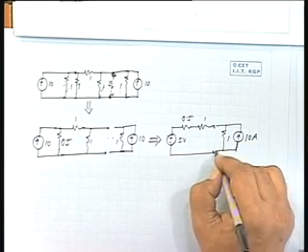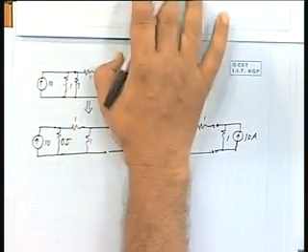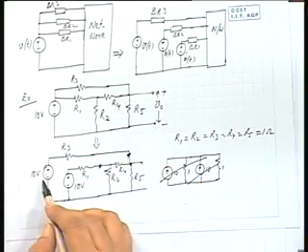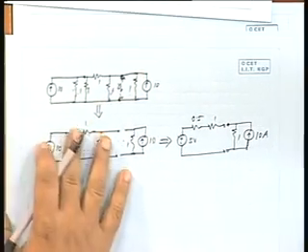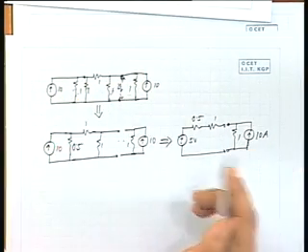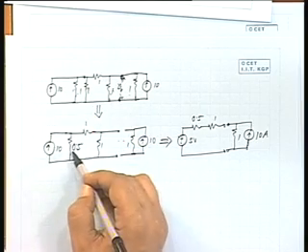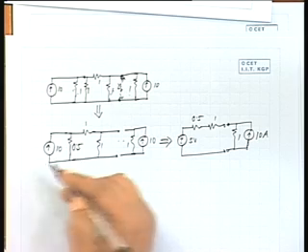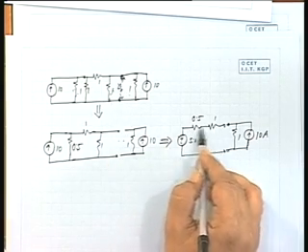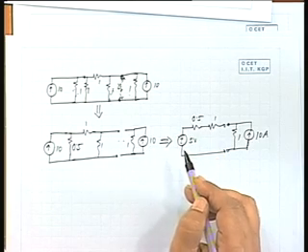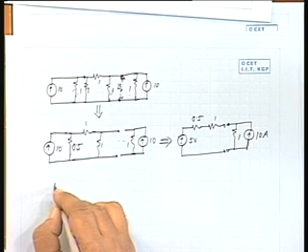Okay. So, we have used the principle of separating the voltage source into two equivalent voltage sources, then the voltage source is replaced by an equivalent current source, and then we are making reductions in the network elements, parallel elements replaced by a single one, then again from current source switching back to voltage source, then you are having two series resistances, put them together, 1.5. So, I can put this as a single current source. What will be the value?